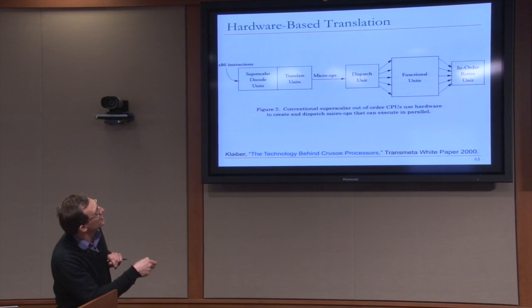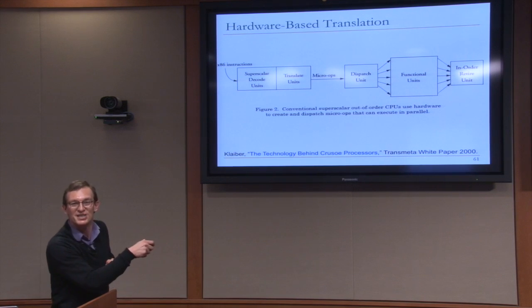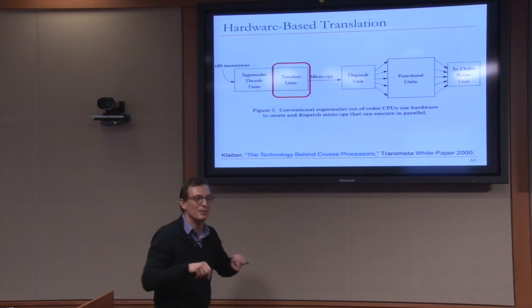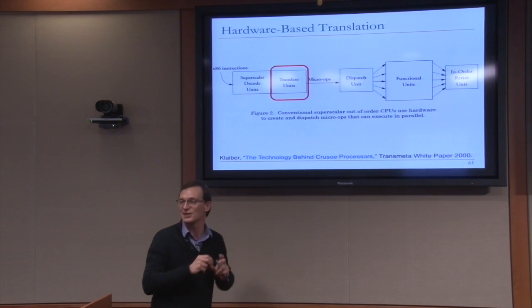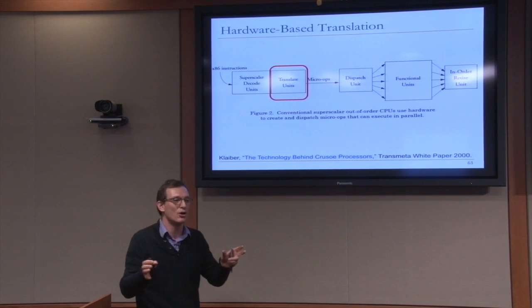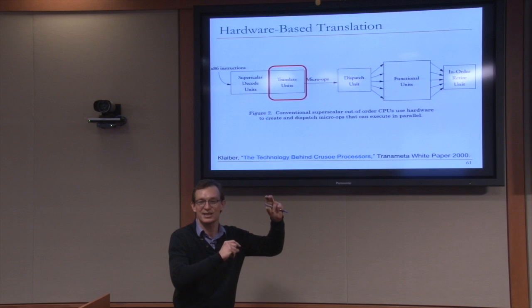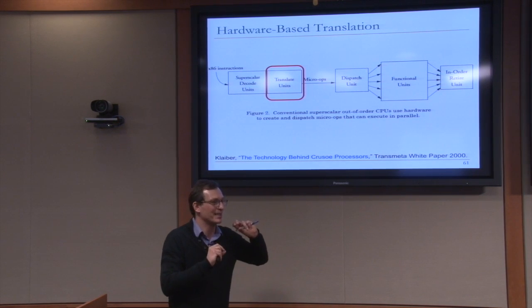But if you look at a processor today, you don't need to understand everything over here. While you're decoding, and this is kind of a cartoonish picture, while you're decoding x86 instructions, you're also translating them into micro-operations. And later, what gets executed is really the micro-operations. The complex instructions do not get directly executed. They get translated into micro-operations. So what you're doing in homework 1, you're taking repeat MOVS and translating into MIPS instructions. You can think about the hardware doing it dynamically.